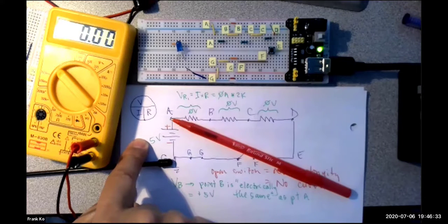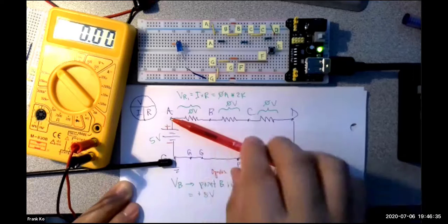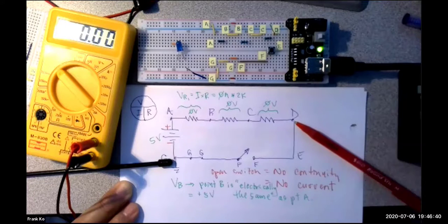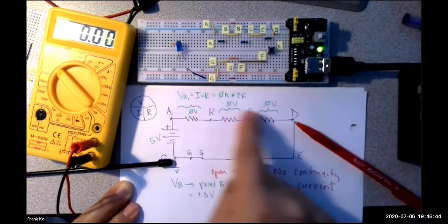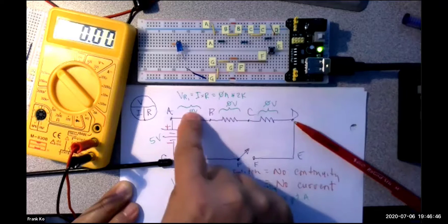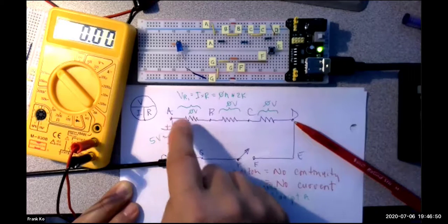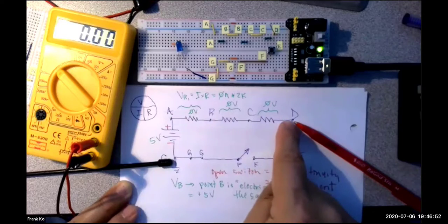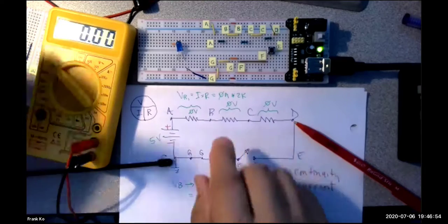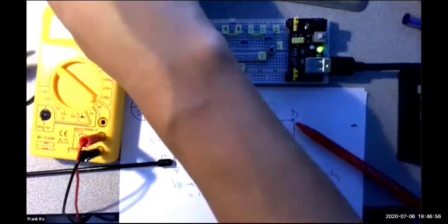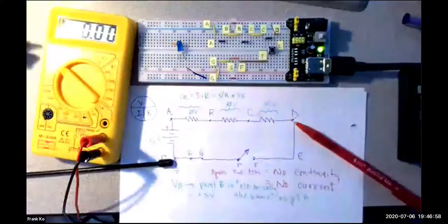5-volt source, yes? Positive 5 volts in this case. So the same at B, same at C, same at D. That's our prediction based on following our calculations of Ohm's law. It's 0, 0, 0. They're physically connected. That positive will be sensed all the way over to here. Let me prove it to you with the measurements. Here we go.